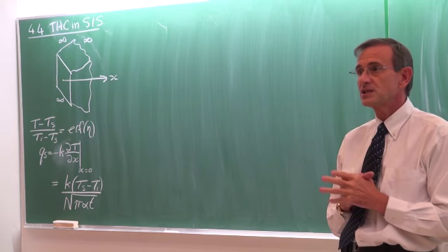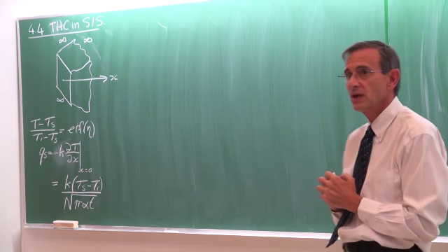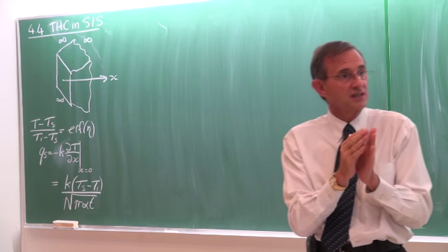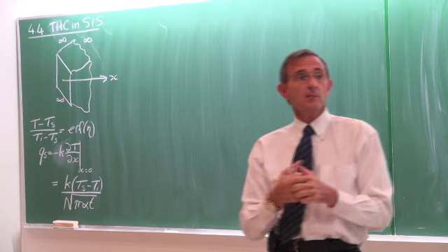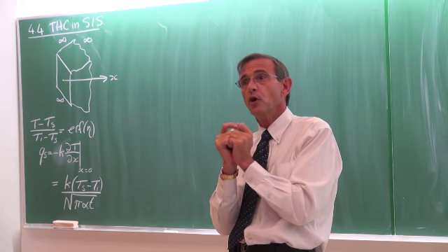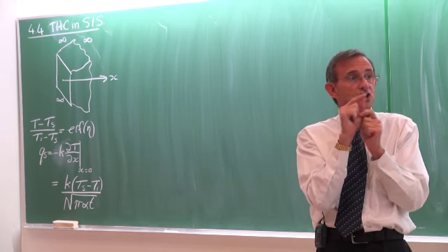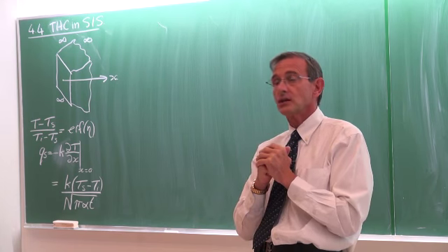The first category was the lumped system approach, and we've already done that. The lumped system approach is where there are no temperature differences inside a body. The equation is very, very simple, but if you use that, you cannot distinguish temperatures at different positions inside a body. They all will have the same temperature.